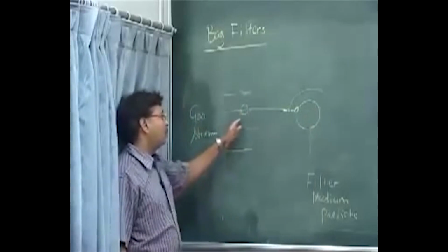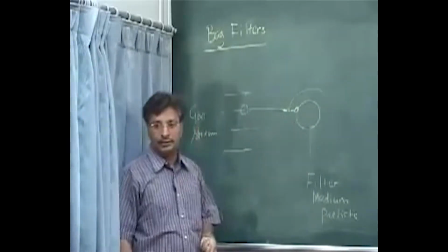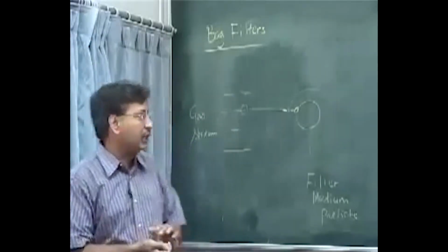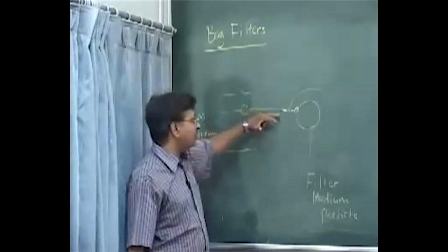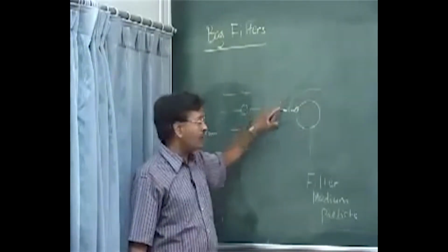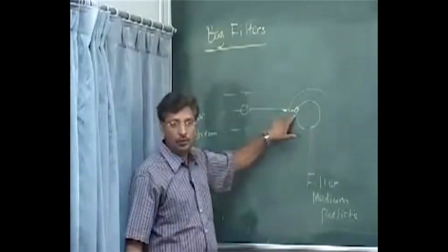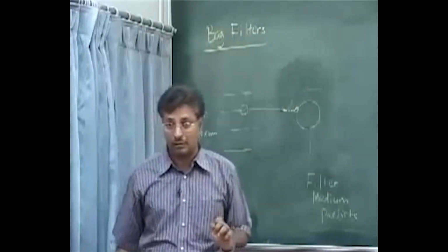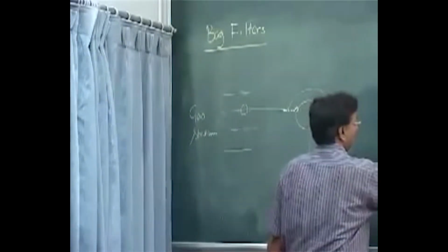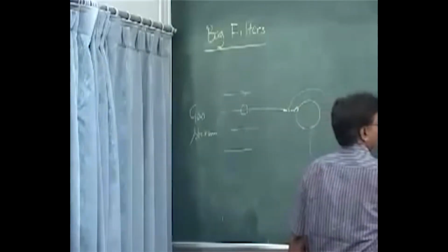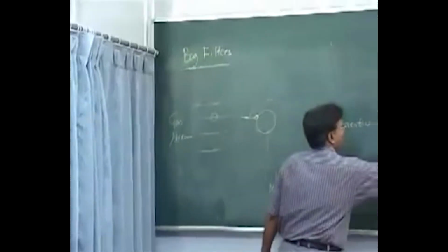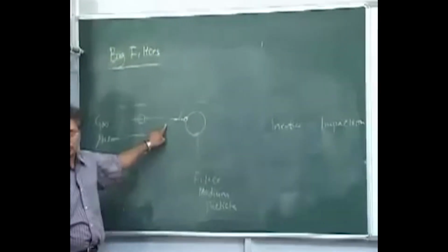The particle is moving because of its inertia. The gas will react to the disturbance. The gas stream will move up. The particle, because of inertia, will continue to move. That is called impaction, if you recall. Okay. So the first mechanism is because of inertia. This is impaction, what I have talked to you about.